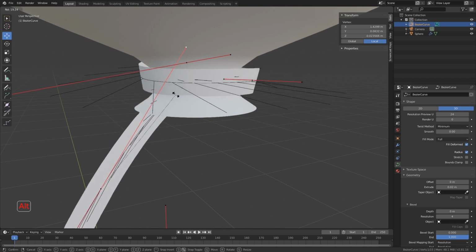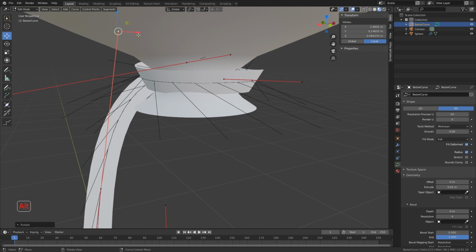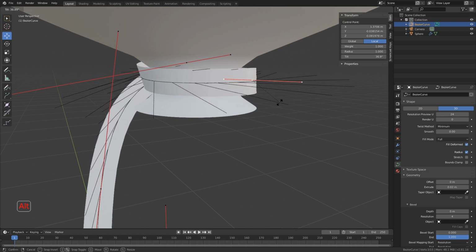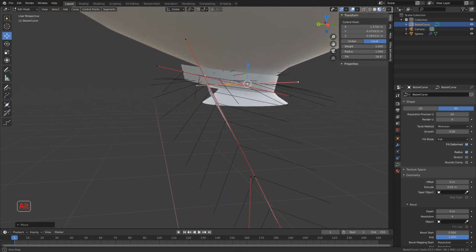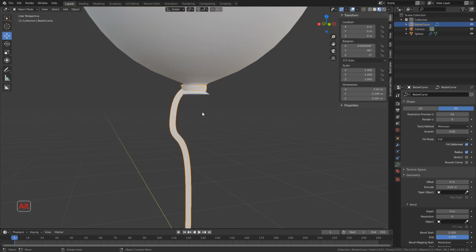So if you want to twist individual points, let's say it looks like this, you can always press Ctrl T, and now you will control the rotational point of each individual vertice. So that's handy. I think this is good for this tutorial. Good enough.